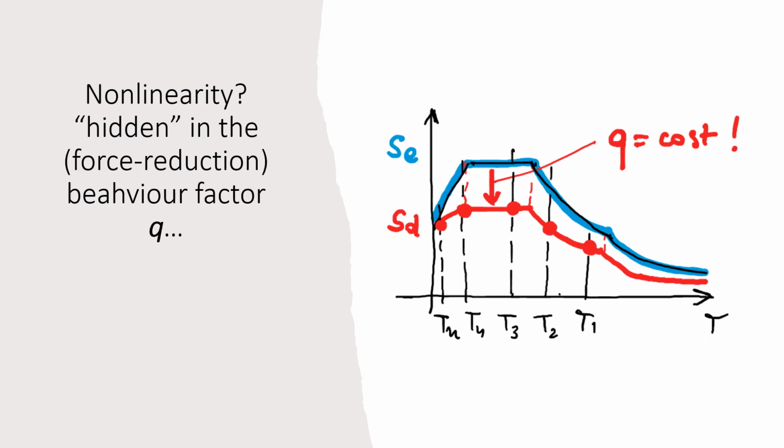It is typically constant. It depends on several characteristics of the building, but in this value again we are hiding, in a conventional safety verification, the damage that we accept occurring in the structures, and assuming its additional energy dissipation helps in reducing the ordinates of the spectrum.